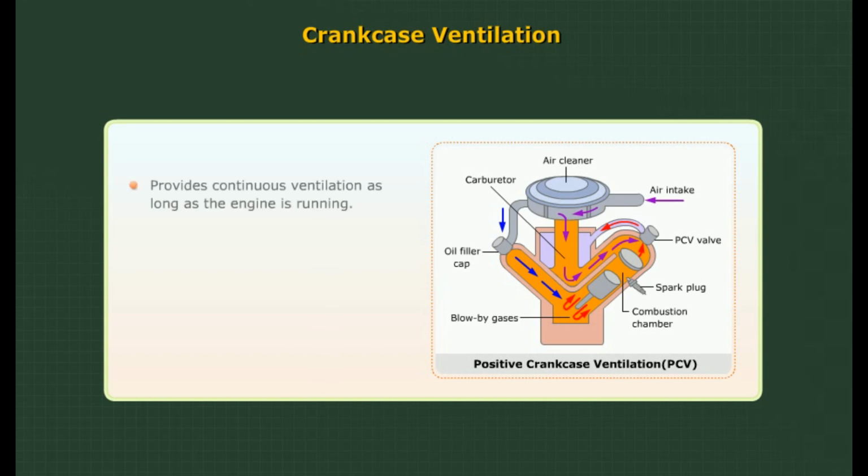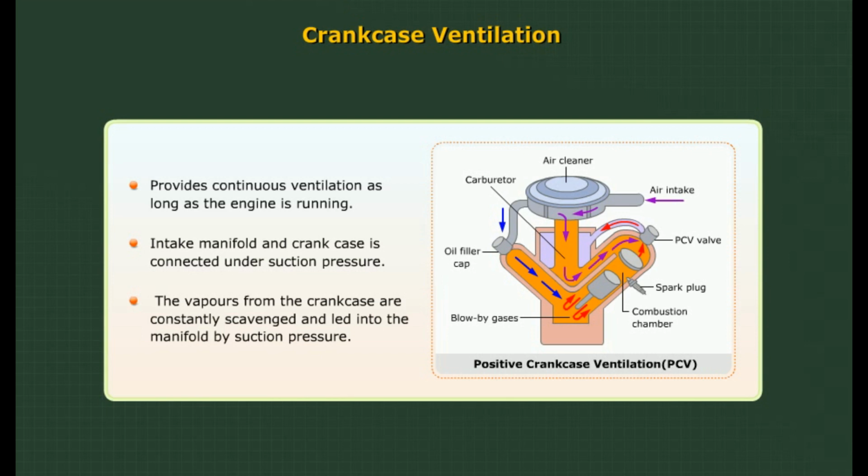Crankcase ventilation. Provides continuous ventilation as long as the engine is running. Intake manifold and crankcase are connected under suction pressure. The vapors from the crankcase are constantly scavenged and led into the manifold by suction pressure.